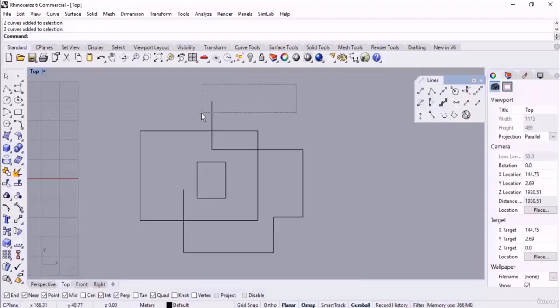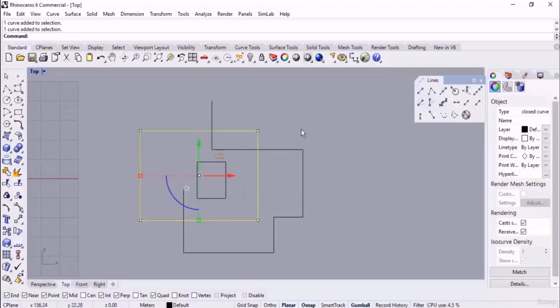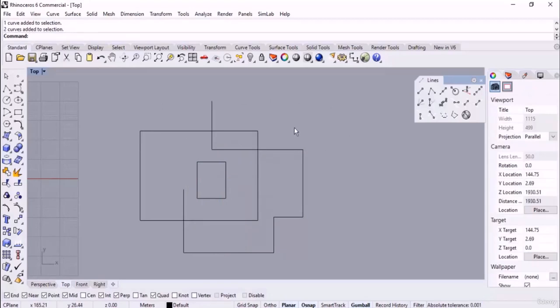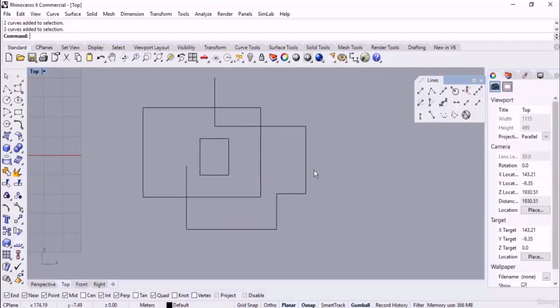What about sketching a window or a frame from right to left? You can drag right to left for a crossing selection. If we cover a small part of the object, then we can select it. This type of selection is called crossing selection, where we drag from right to left.